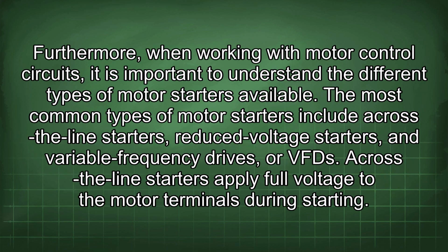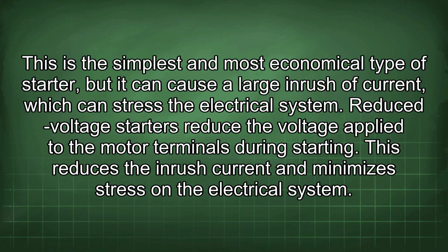Furthermore, when working with motor control circuits, it is important to understand the different types of motor starters available. The most common types of motor starters include across-the-line starters, reduced voltage starters, and variable frequency drives, or VFDs. Across-the-line starters apply full voltage to the motor terminals during starting. This is the simplest and most economical type of starter, but it can cause a large inrush of current, which can stress the electrical system.